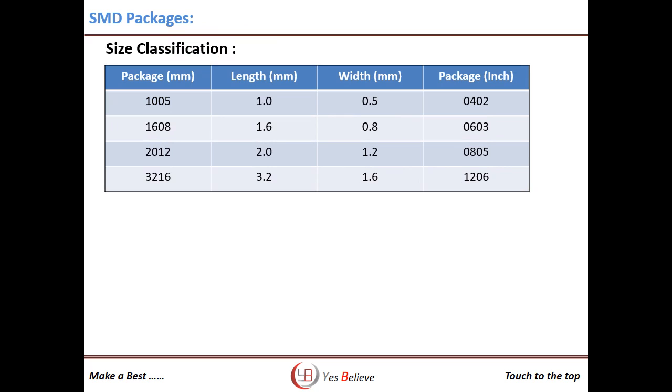As explained, SMD components are usually smaller than through-hole components and are designed to be handled by machines rather than by humans. The electronic industry has standardized the package shapes and sizes. Here, the sizes of components are explained as per their packages. The 1005 size is in mm and 0402 is in inches. We suggest using mm because the machine uses mm units. So do not get confused, you need to use a common unit only.